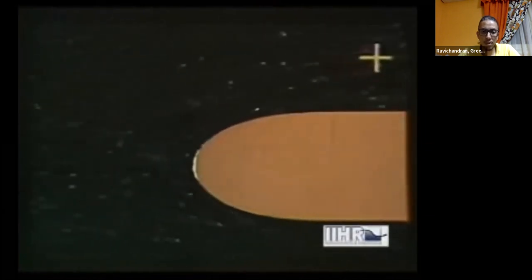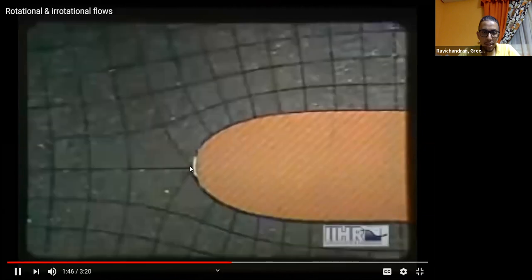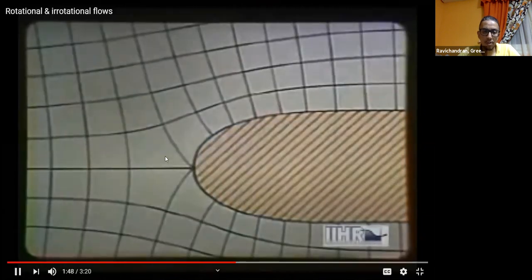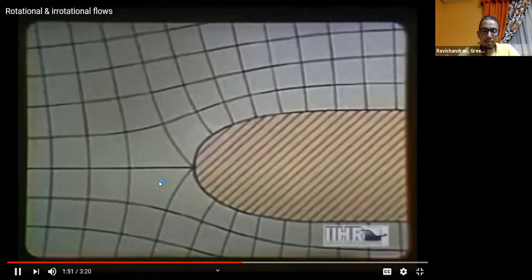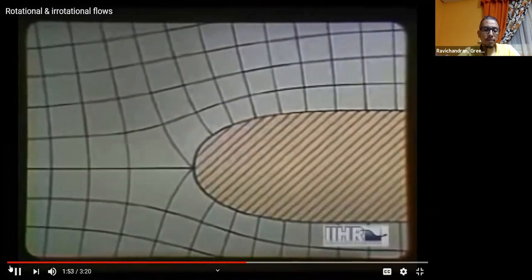Flow in concentric circles is not the only kind that is sometimes highly rotational and sometimes almost irrotational. Uniform parallel flow between walls is usually rotational, where the particle is rotated along one axis. Non-uniform or unsteady flow that is rapidly accelerated is very nearly irrotational. Even if there is some turbulence, it can still be irrotational flow, and it can be approximated graphically or mathematically by the construction of a network of streamlines and normal lines.